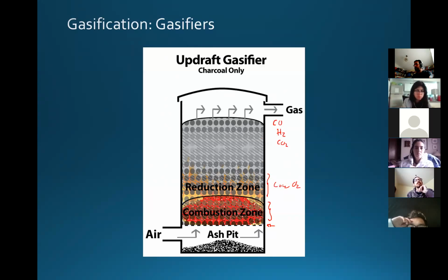This gasifier is not the ideal case because you obtain a dirty syngas that is cold. If you remember when you did your mental map, you found that you obtain a syngas, a mixture of CO and hydrogen. Because the gas that we obtain here is not just carbon monoxide and hydrogen, we have a little bit of CO2 and other components, we call it a dirty syngas.